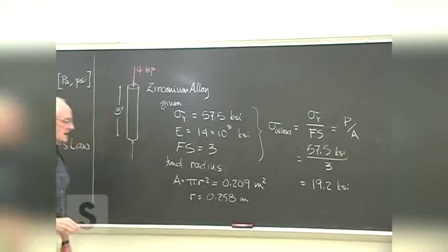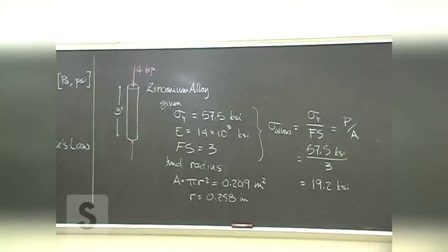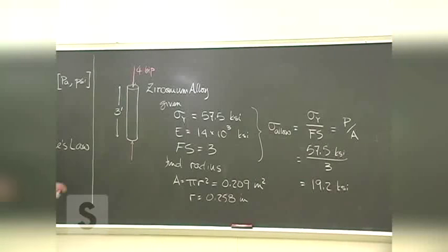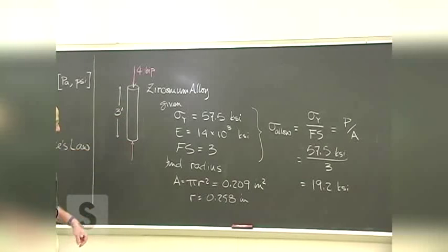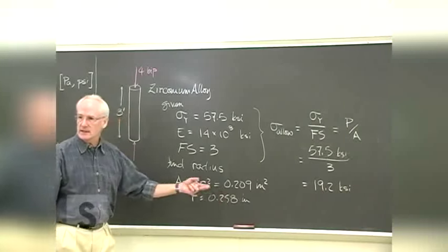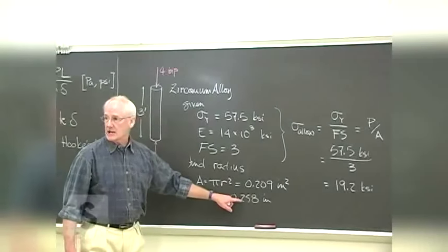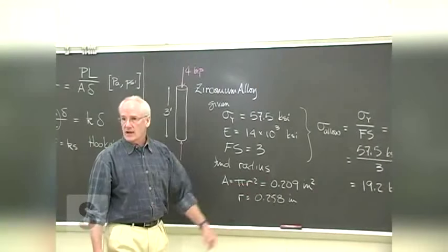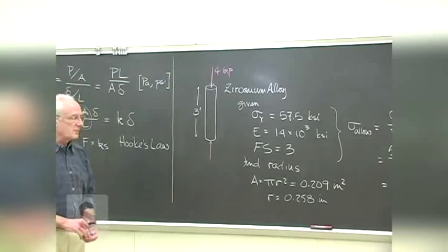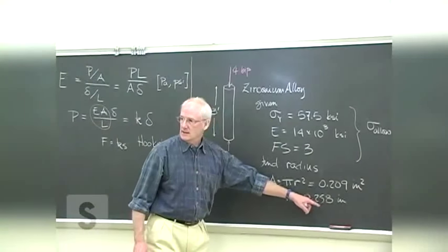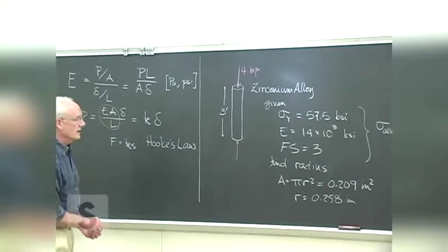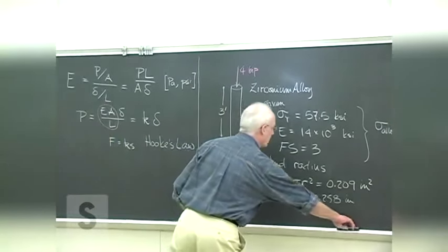0.258 inches, probably then, well, since this isn't a standard piece, you can make it to any radius you want, since it's probably a one-off piece for whatever reactor. But if you're looking at some bolt or something, you'd want to make sure that you have a standard radius so you don't have to custom make every one of these parts to that exact radius. You might want to just make it 0.3 and buy stuff off the shelf that way.